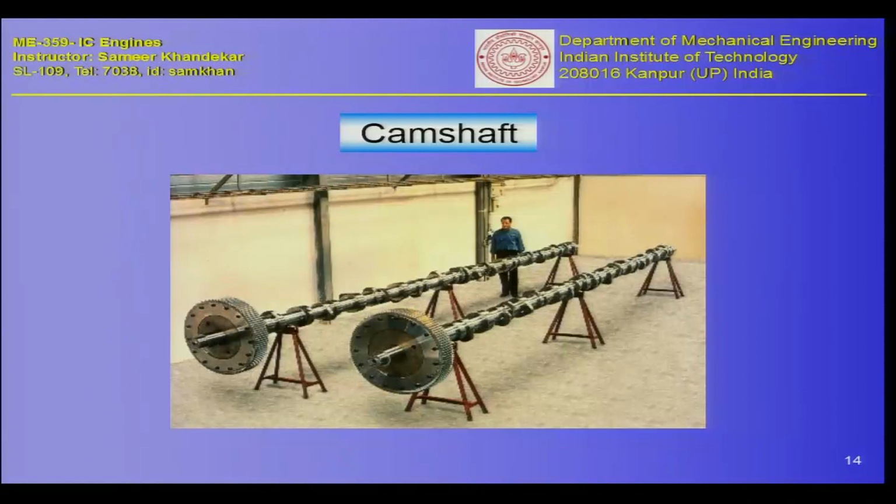For marine engine operation, it's an inline arrangement, and there are many cylinders which are being, let us say, catered by this particular camshaft, and for every cylinder you have two camshafts operating the two valves, for example, of a large marine engine. So here you can see the dimensions of the camshaft, which are rather huge as compared to small camshafts which are there in smaller engines or smaller automobiles.